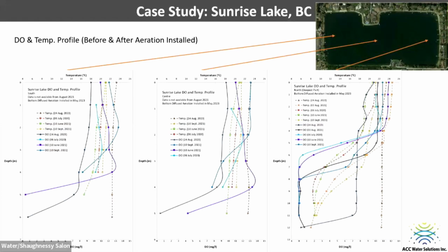In other words, we know the average sediment oxygen demand of most water bodies in the prairies is a certain amount given a certain amount of productivity. So we can still create models and still give you a fairly clear idea if it's going to work or not, because again, sometimes huge monitoring programs and scientific studies just cost money.